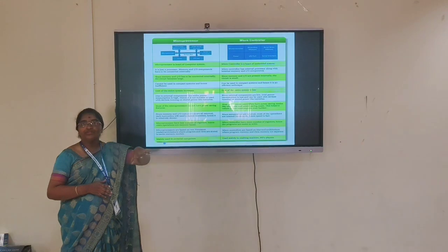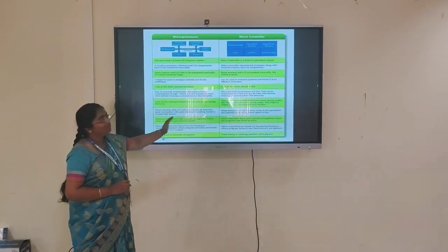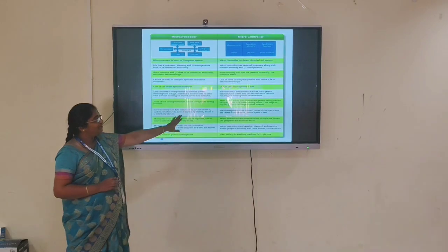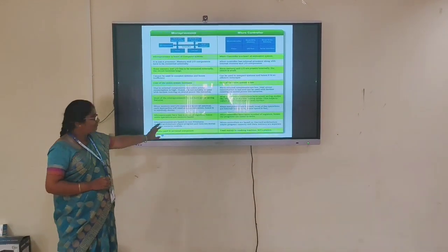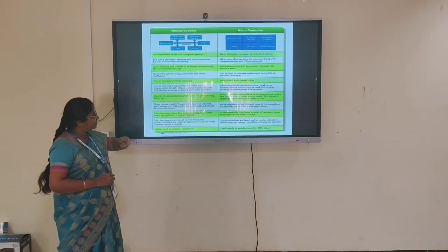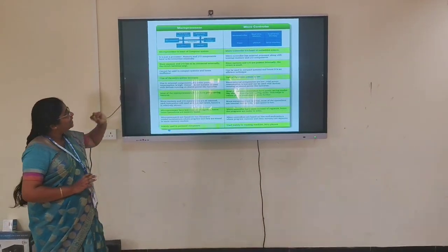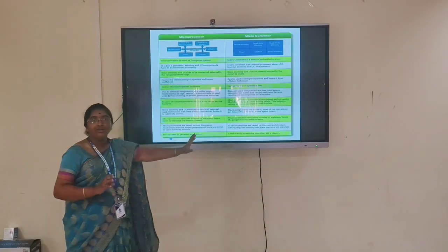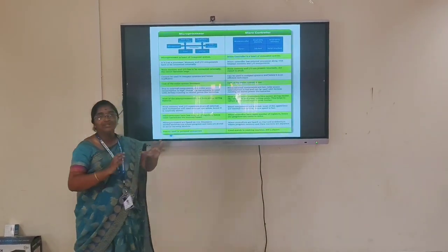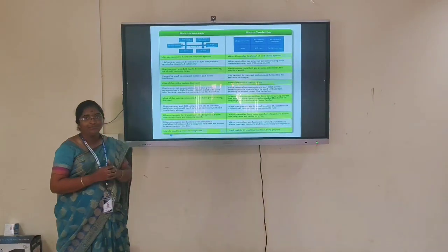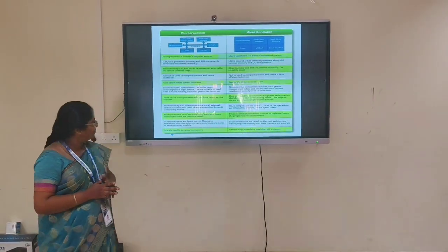Most microprocessors do not have a power saving mode. A microcontroller does have a power saving mode. Next, the microprocessor has fewer registers, hence more operations are memory based. The microcontroller has more registers, hence the programs are easier to write. A register, as I said, is a temporary storage area.